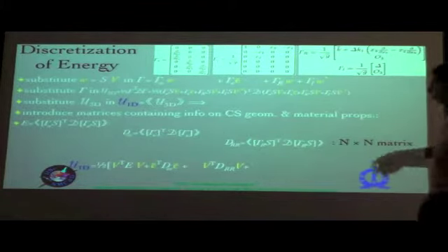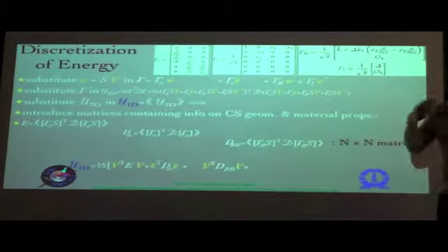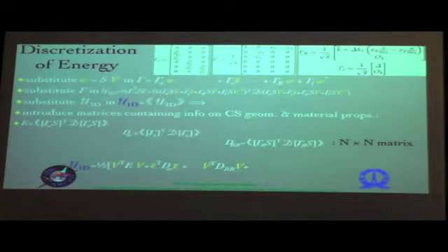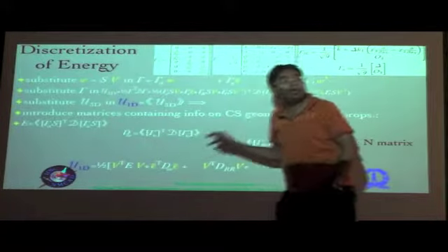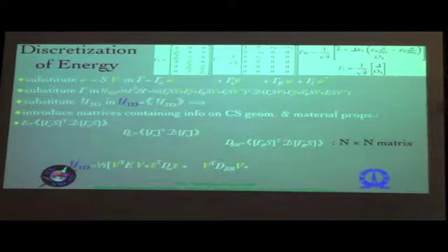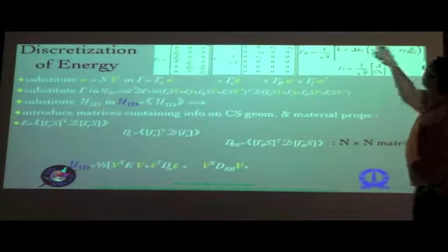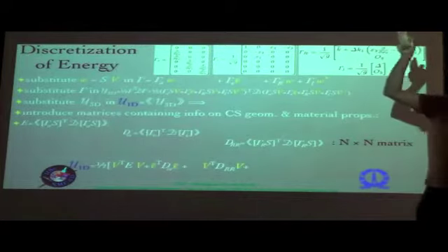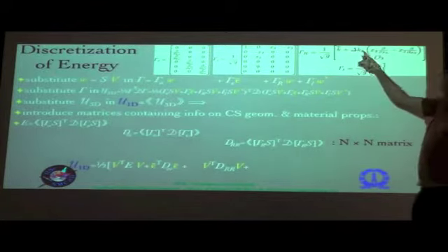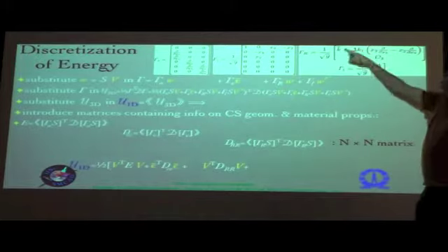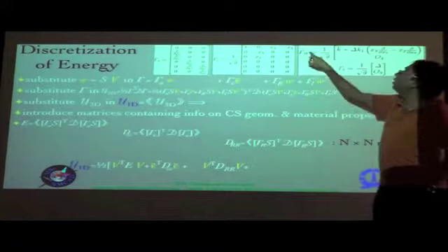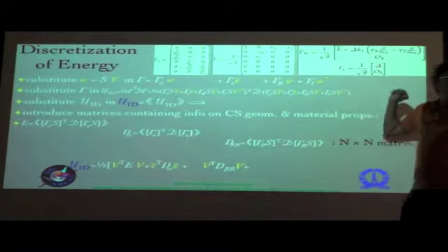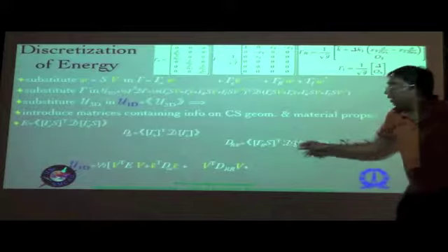Similarly, the third term, which involves the contributions of the initial curvature, primarily, though of course initial curvature is contained into these as well. This is a direct primary contribution from the initial curvature, DRR term, because it basically comes from this gamma R, and if there were no initial twists and curvature, you would see that K1 and K tilde would go to 0, this entire matrix would be equal to 0, root G of course would be 1, and therefore your gamma R would be basically zeros, and therefore you would not have anything at all over here.